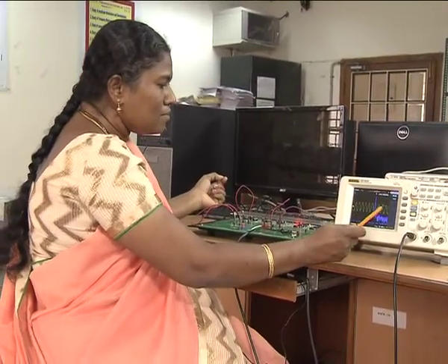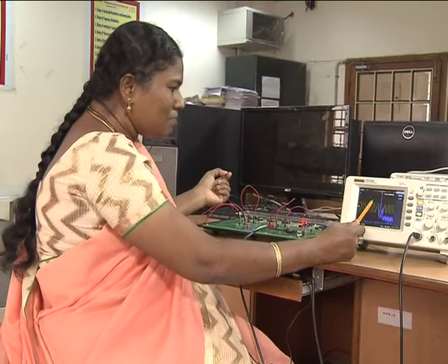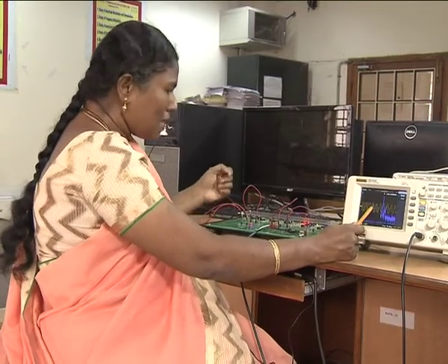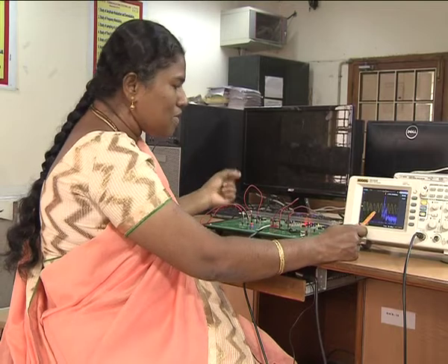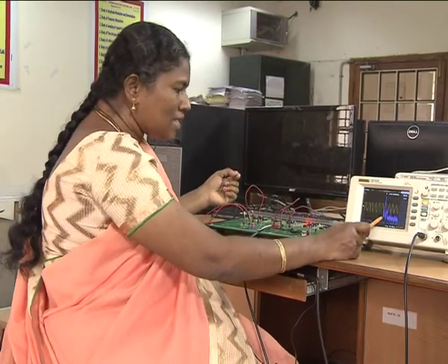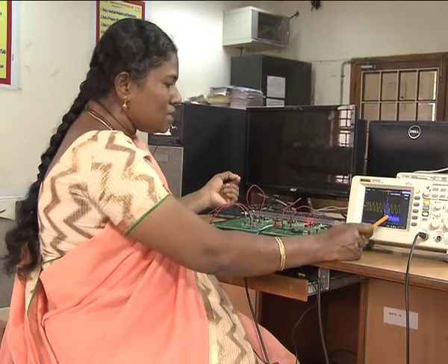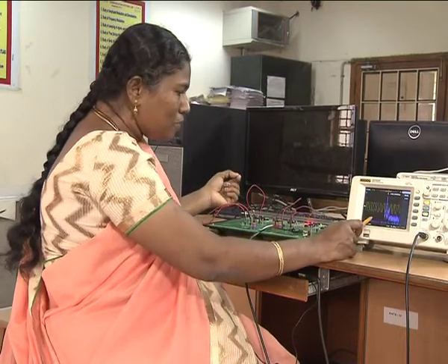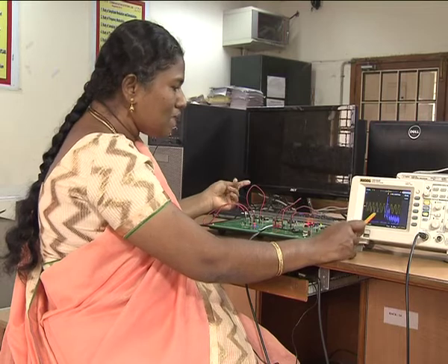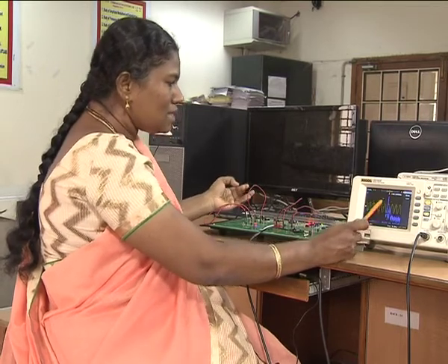F max is the maximum frequency that is created with respect to the maximum voltage provided to the VCO. F min is the minimum frequency that is created at the output with respect to the minimum input voltage. So, we compute beta, which is nothing but the modulation index for the FM modulated signal, as f max minus